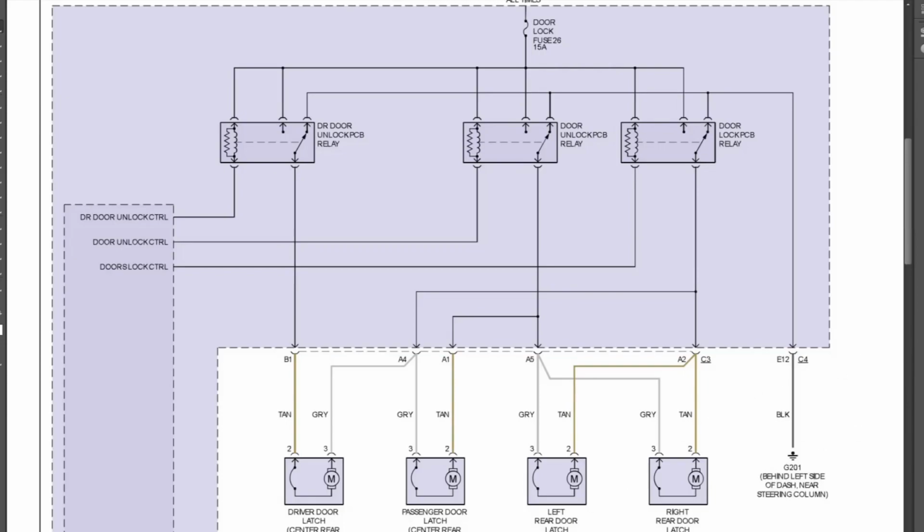So you have relays here, but here's your driver's door locks here. And there's a bunch of relays going on. Now this is buried, you can see this color here, it's buried inside the BCM. But all you're checking for is the circuitry of the motor itself. Let's just follow this one. Pin 3 here, all the way up to A4, it goes up through this door lock relay. Okay, now this is a 5-pin relay, and it's going through the normally closed set of contacts, so you're not touching anything. You're not touching any of the buttons. It goes up, it goes to ground.